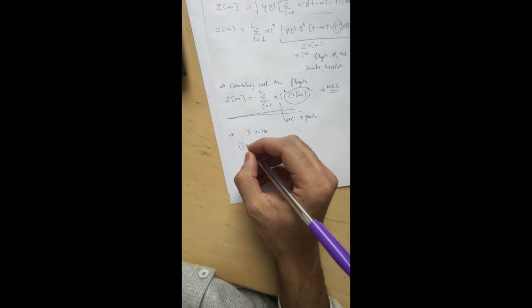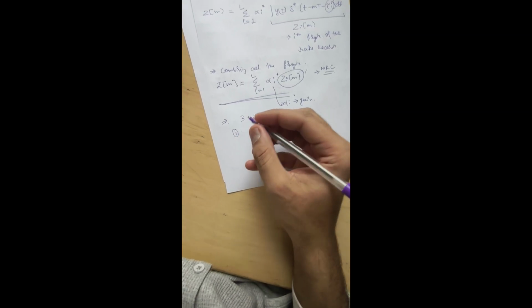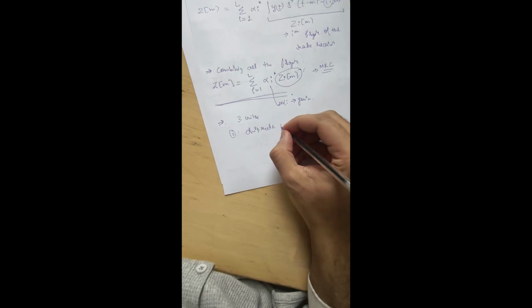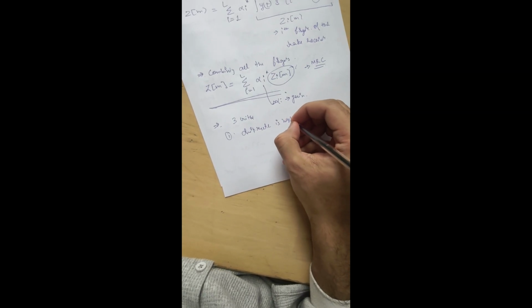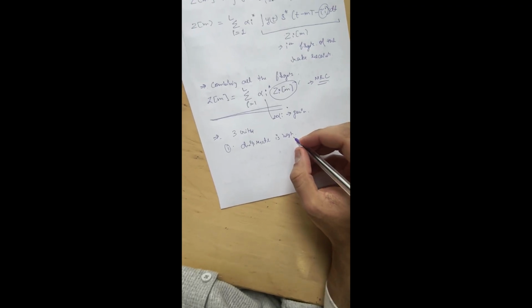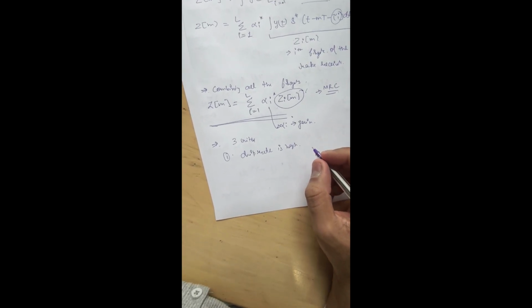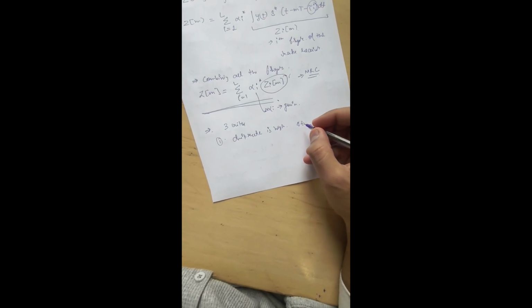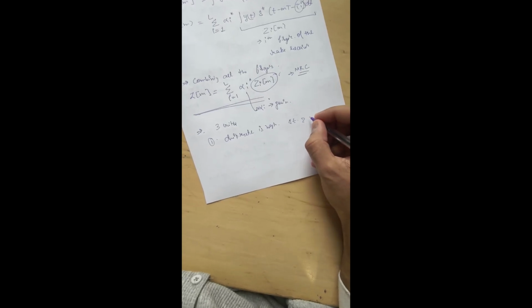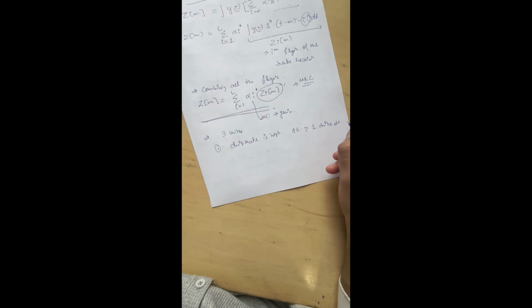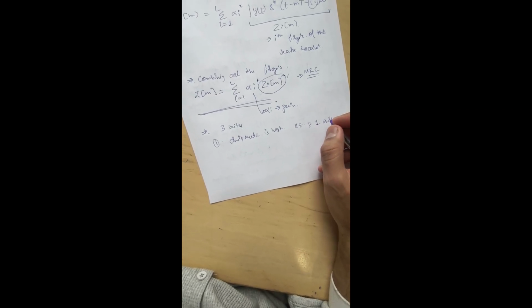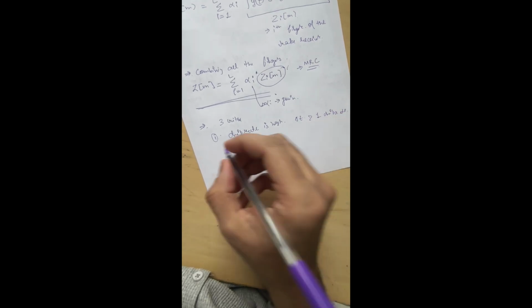First of all, this derivation only works when the chip rate is high, and for direct sequence spread spectrum, the time difference between the paths should be greater than one chip duration for this to work. And since the paths are approximately orthogonal, it allows the fingers to separate them.